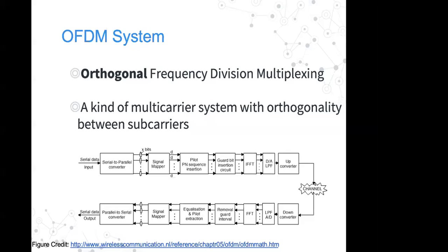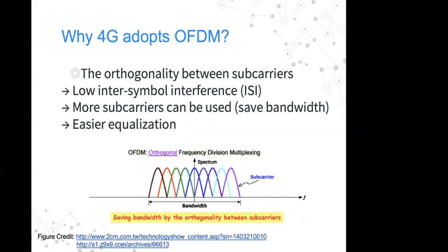The main problem is strict orthogonality. Suppose some deviation is there between the transmitting frequency and the receiving frequency, that is sine of omega naught t plus delta of t. The delta of t is an additional phase, and this additional phase will lead to a problem of synchronization.